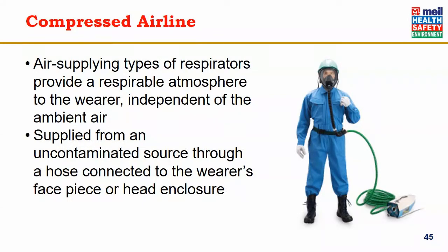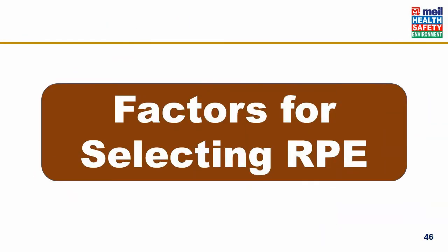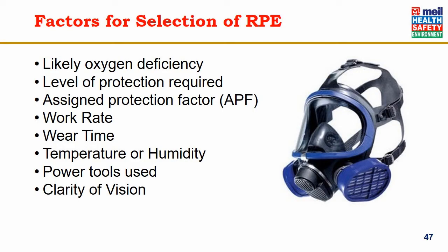Factors for selecting RPE. What are the factors to be considered before selecting respiratory protective equipment? Likely oxygen deficiency, the level of protection required, assigned protection factor, work rate, work wear time, temperature or humidity, that is ambient factors, power tool usage in enclosed space or anything, clarity of vision required. Clarity of communication while wearing the RPE is another issue.